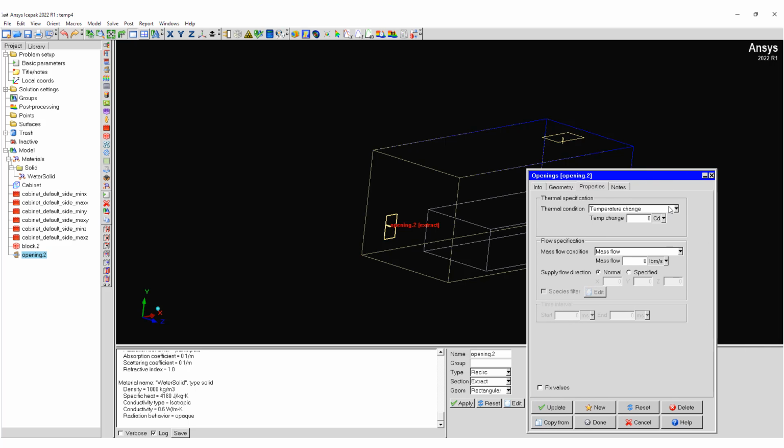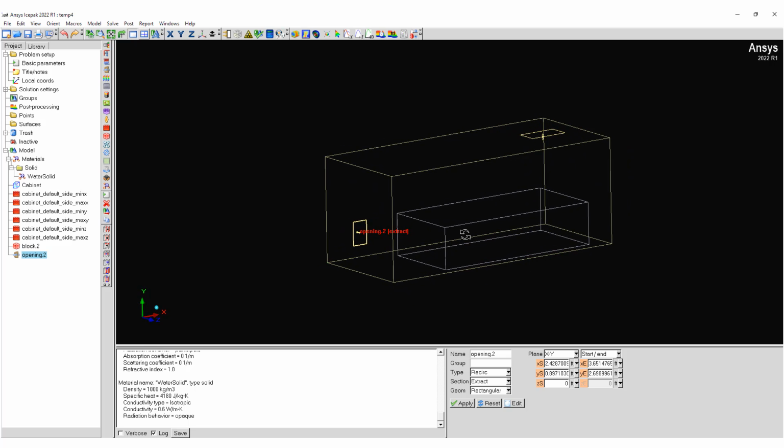So we can specify a temperature change or heat input or extracted. We can specify a volumetric flow rate in cubic feet per minute. Okay, I'm going to make up some values here. I'll just put 1,000 cubic feet per minute of flow rate, and we can extract energy from this. So let's do watts, maybe minus 10,000 watts. We're going to try to keep this thing cool, and we'll see what temperature it ends at.